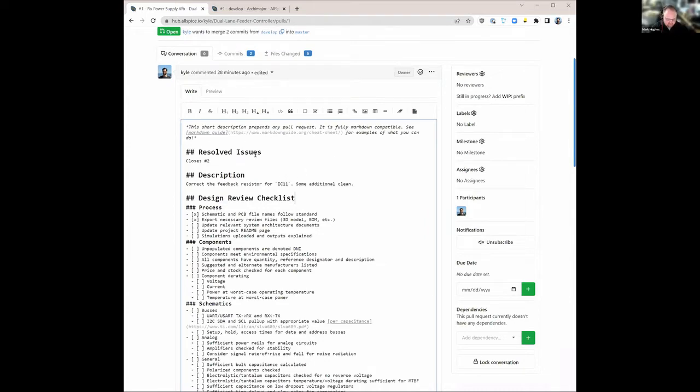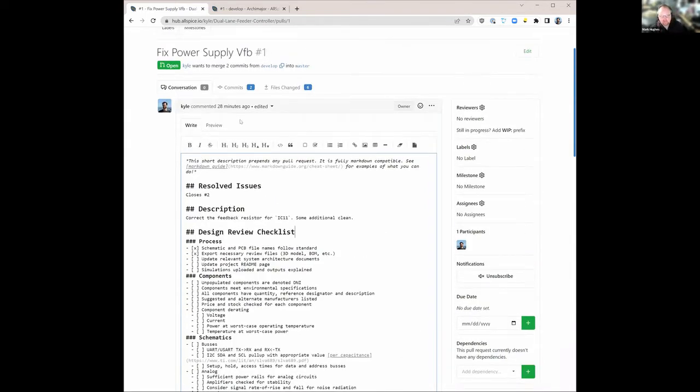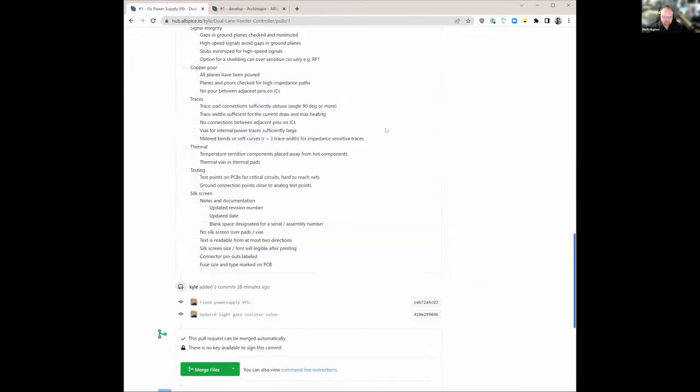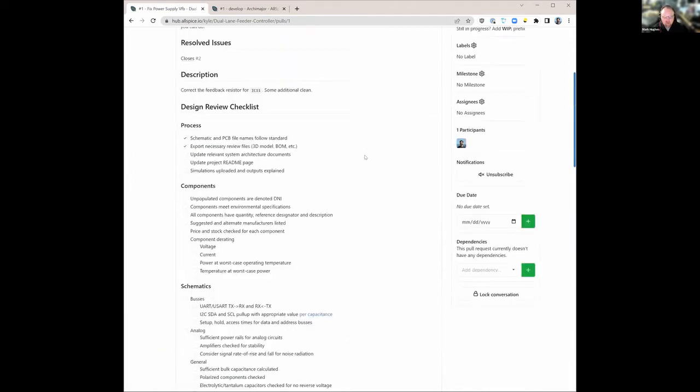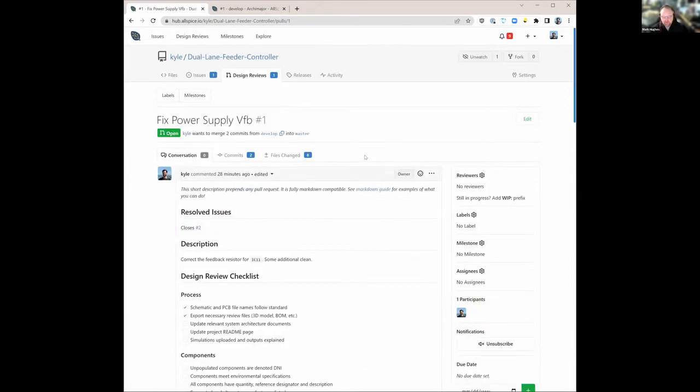All right. Yeah, the design review is a little bit different from what you might do on your board, an ERC, electrical rules check, making sure there are no shorts on the nets or anything like that. Or even your design rules, where you go to your schematic and say, okay, I've got a 100-volt net here, it needs a minimum of, say, 15 mil spacing to any other net. Well, you're looking for other things too. Engineering is such a complicated subject, you can get bitten by so many little things over and over again. It always helps to get a second or even third set of eyes on a project.